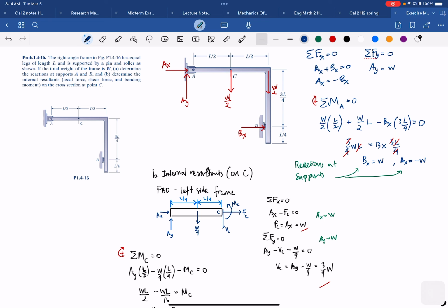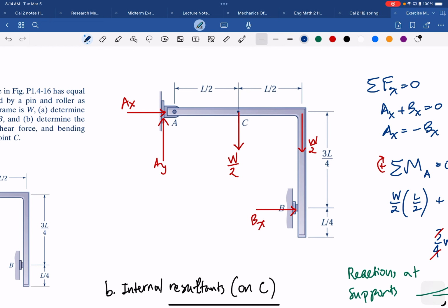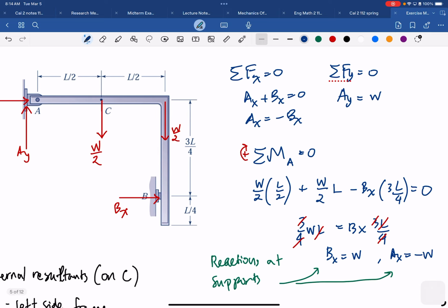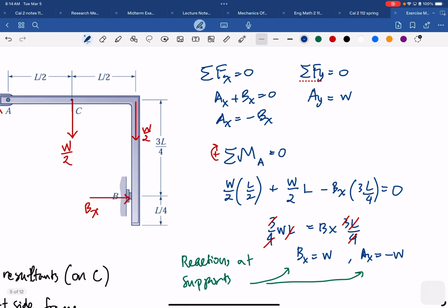First, we are going to draw the free body diagram and put in all the reaction forces. Basically, in chapter 1, every procedure after you draw the free body diagram is taking the equilibrium. By taking equilibrium, you take the forces on the x-axis, y-axis, and the moment. After all that, you will get everything the question asks.